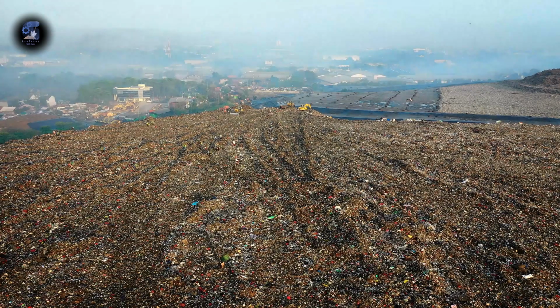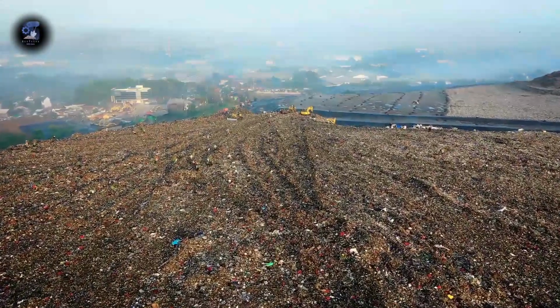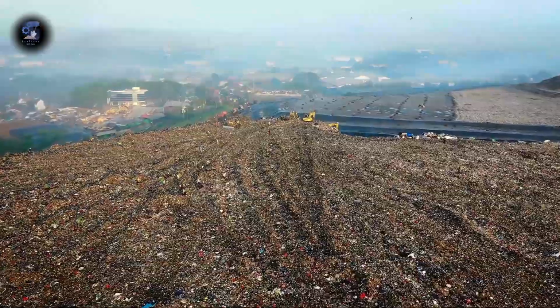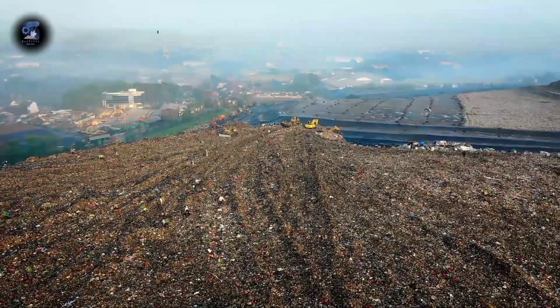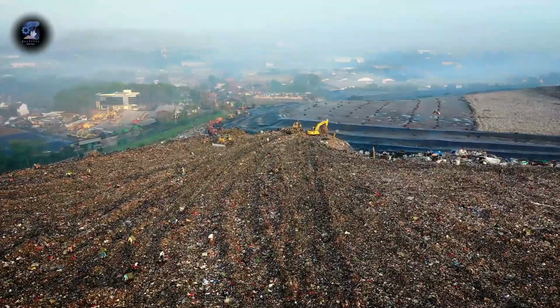Site selection of the landfill construction is critical. The site should have stable subsurface soil conditions, and the groundwater table should be deep enough not to interact with the landfill to avoid contamination. This is one of the reasons why landfills are usually located on high ground.